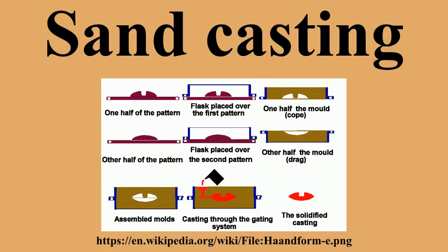In 1962, Dansk Industri Syndikat (DISA) invented a flaskless molding process by using vertically parted and poured molds. The first line could produce up to 240 complete sand molds per hour. Today, molding lines can achieve a molding rate of 550 sand molds per hour and require only one monitoring operator. Maximum mismatch of two mold halves is 0.1 mm.